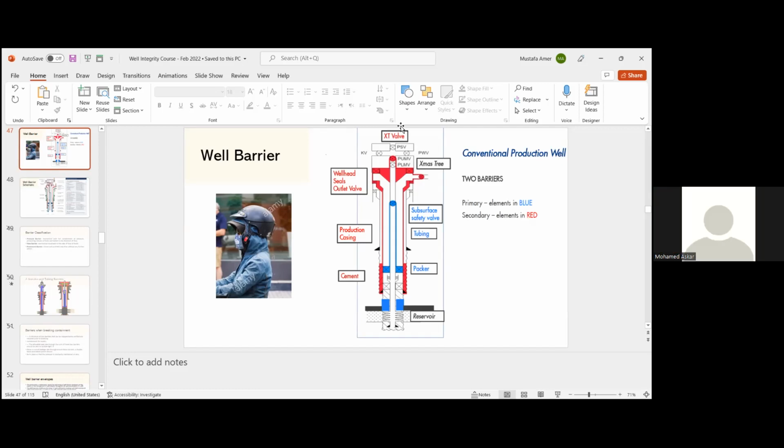Thank you, Mustafa. I may have some points about the question that was asked about the biannulus fluids. Yes, please. Okay. You may have some investigation actions like running logs that have leak detection capabilities, which can use ultrasound methodologies that can hear behind the casing. You can detect the depth of the leakage, just for knowledge. And there are some methods for well intervention. Some few companies now supply tools to intervene in the annulus between two casings and dump some cement.